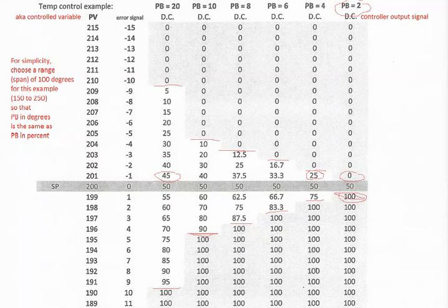In fact, when you are tuning a system, cranking up the gain to where it oscillates gives you good information. You can see the response time of the system, how fast it responds, and things like its inertia and its thermal mass if it's a heating system and so on.